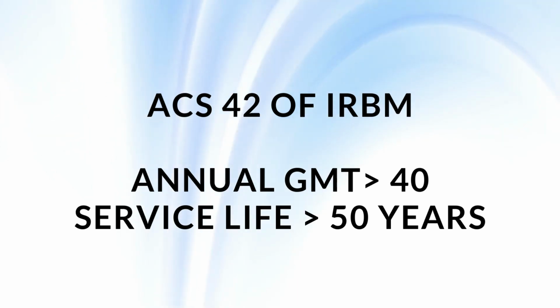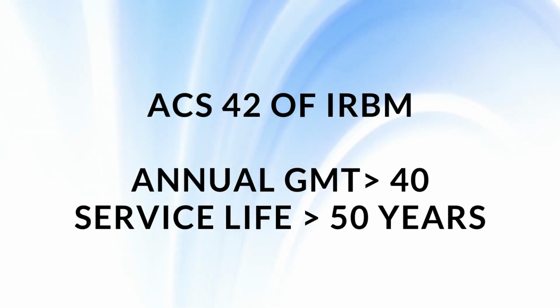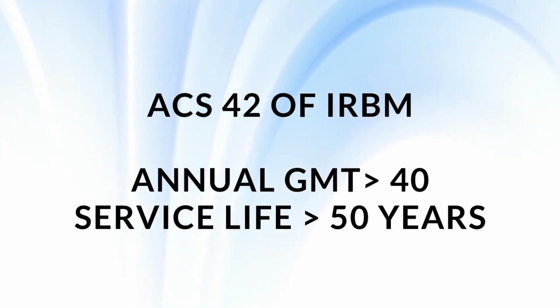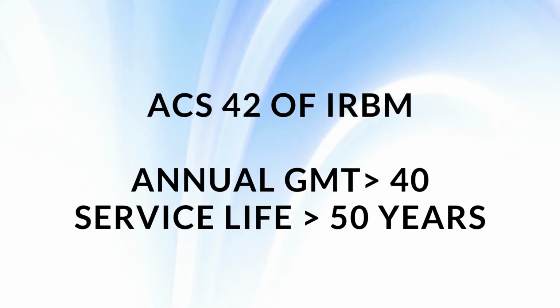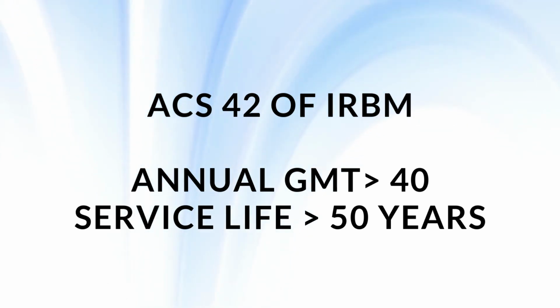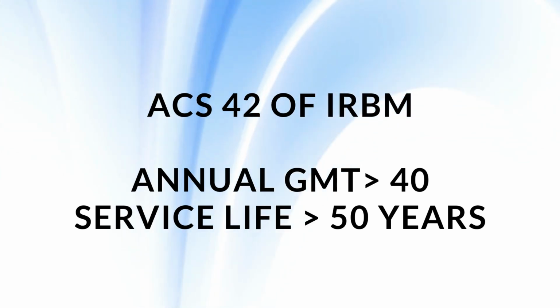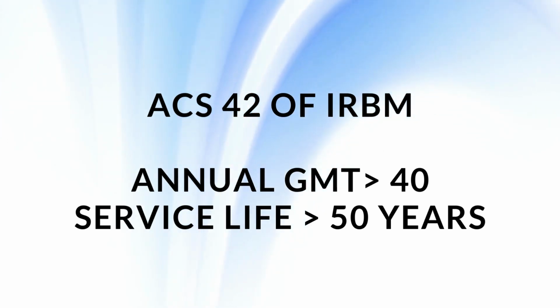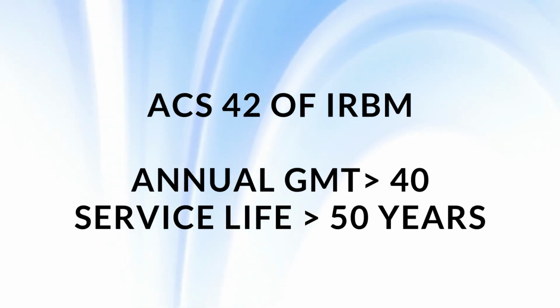As per ACS 42 of Indian Railway Bridge Manual, the bridges which are en route having annual GMT of 40 and above, and which have completed an age of more than 50 years, shall be systematically assessed for residual fatigue life and will be planned for extensive monitoring till retrofitting or final replacement.